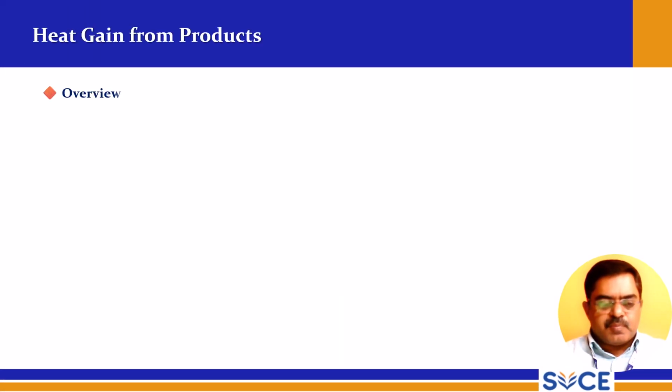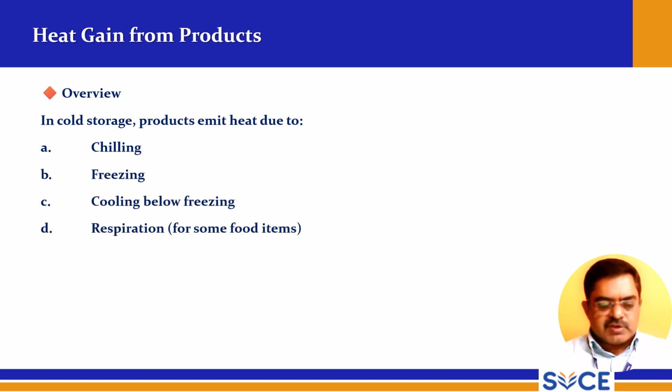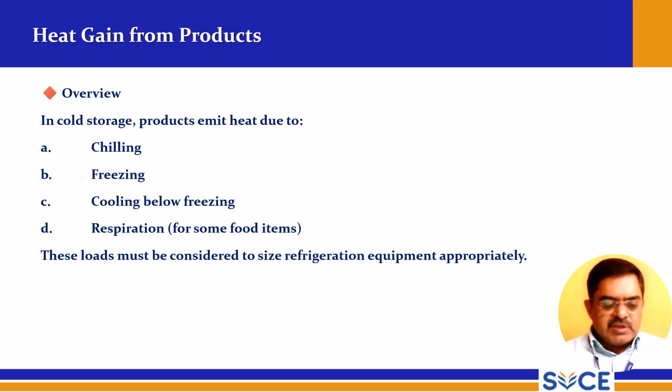So, heat gain from products. The overview is like this. In cold storage, products emit heat due to chilling, freezing, cooling below freezing, and respiration for some food items, and these loads must be considered to size refrigeration equipment appropriately.